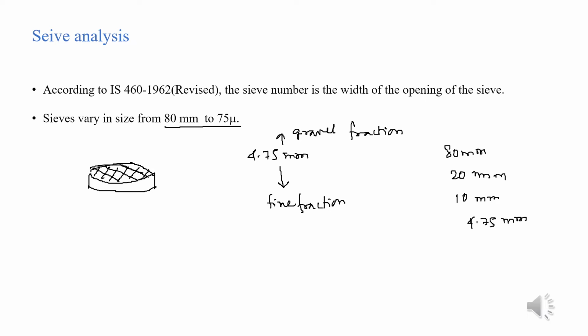If particles smaller than 75 micron are present, like silt and clay, then we undergo sedimentation analysis, which will be taught in the subsequent slides.